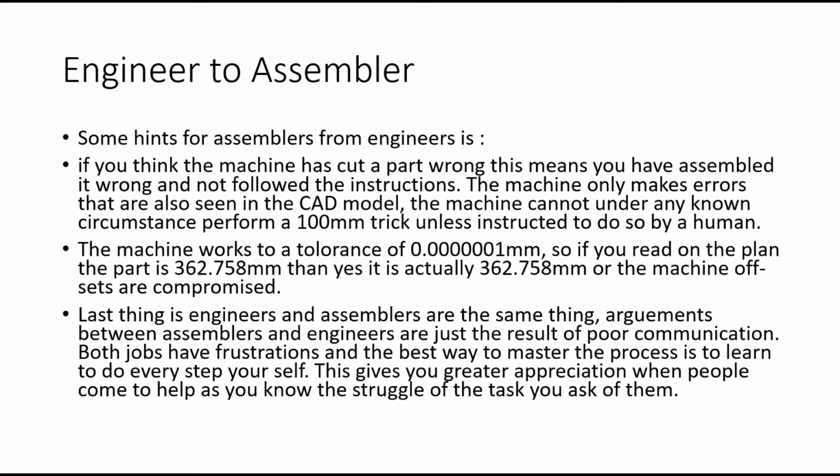And this is all real stuff. I only know this from experience and having done it before, because I've been there on the floor having arguments with engineers going like, mate, show it to me on this tape. It's like, dude, it matters. And it really does ultimately, especially with tool sizings. If you're using Imperial tools, they're going to have ridiculous microfraction offsets. Use whole number metric tools. It's awesome.